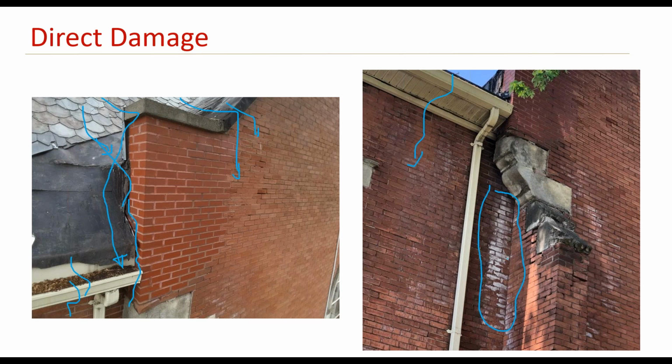The problem with that is, with time, you're washing out the structure, the chemical components of the bricks, and the bricks start reducing in size, as we see here, and we start having deterioration within the mortar, and the bricks would start falling off. And the same thing happens to the concrete corbels here. We see some cracks, we see spalling, and with time, all this would fall, and we have a direct damage to part of a building envelope due to a failure in another part.